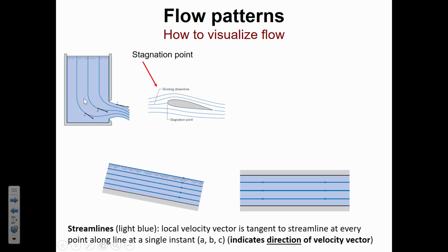And in this case, as water is flowing down through a tank and discharging through an orifice, we get a little bit more information. Because we can see that when these streamlines are getting closer together, that indicates an acceleration. So think about as the water approaches this opening, it's accelerating. There's a high velocity as the water discharges out of the orifice because you've got an opening in the tank that's below the water surface, and so there's some pressure down here, and that pressure is forcing the fluid